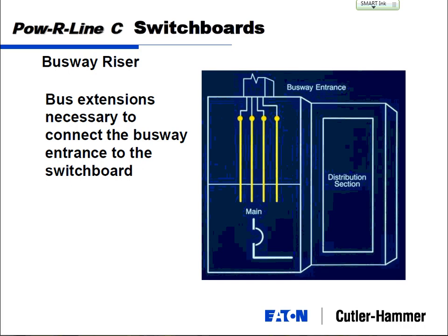And I'd say busway is very common in long runs. If you've got a big campus, a big lab building, like a big warehouse, and you've got to go from one side to the other, busway is going to save you a ton of money in your design, from the installation standpoint, not having to worry about voltage drop.